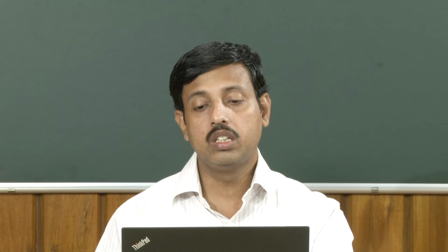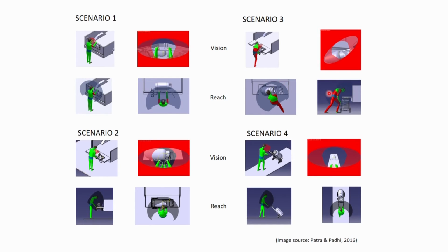In scenario 3, many of the body parts are in red color. It means beyond the comfort range of motion. So although this is a momentary activity, it will not create that much problem, but if some design modification can be done, then this will be good to avoid any musculoskeletal disorder or any problem related to disc pressure also.